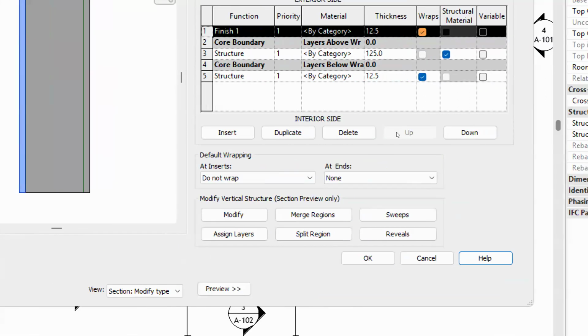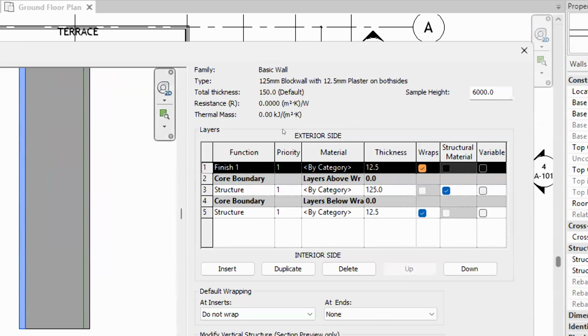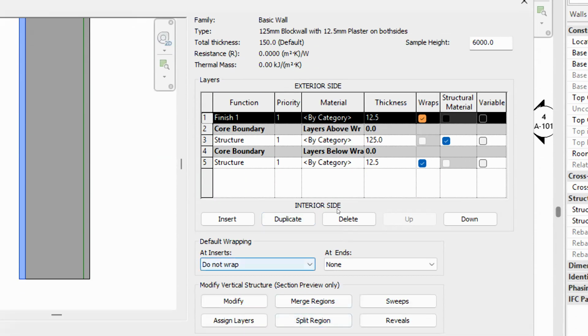There's no other shortcut than to know how to use all of these things here. So if you know how to use all of these things here in this dialog box, then you can tell yourself that, when it comes to Revit walls, you understand what Revit walls are. So you can design any wall of a type that you want in terms of basic wall. So be it a wall with a honeycomb design, be it a wall with any skirting, reveals, or wall with insertions or anything, the tools are there that you can use to create them.